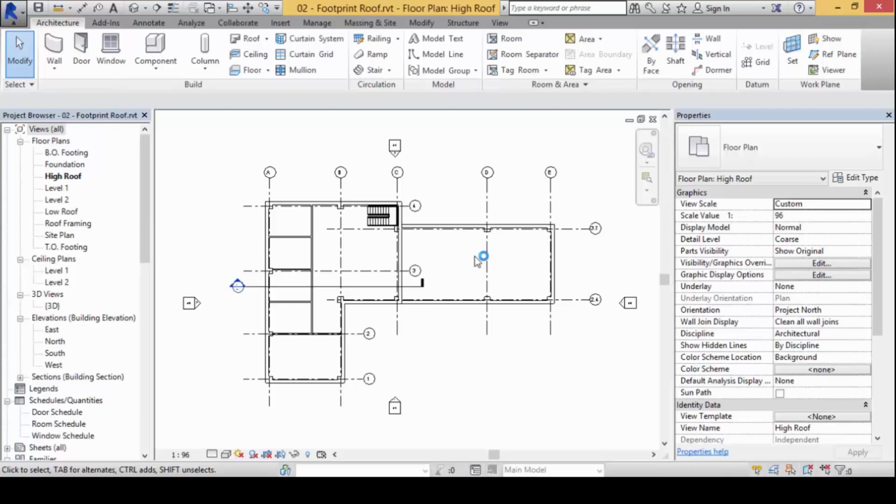Okay, if you look at the toilet, if you're ever in any of those toilets, any toilets at all, it is almost never flat. Often they're slopey, very, very gradual, very, very gentle at that. There is a minimum control for gradient. The minimum control is 1:200. Why 1:200? Because 1:200 is almost deemed as the minimum, the most shallow gradient that water can still move.